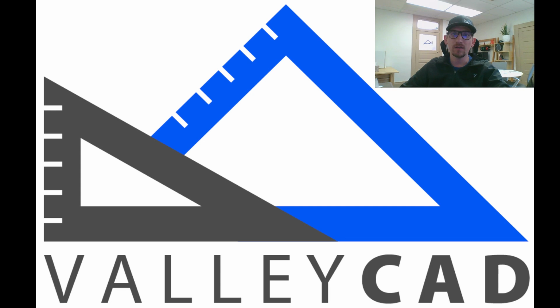We came in and said, hey, our overall distance is 4 1/4, so we know that is never going to change unless I came in with some cut and lopped off the edge. But I'm setting up a rule that this is an overall distance of 4 1/4. Then from there, we just did a standard cut. So imagine that tool coming in, kissing that face a certain distance in, and then cutting it. And then you have Cut Extrude 2, which is that standard little slot there.